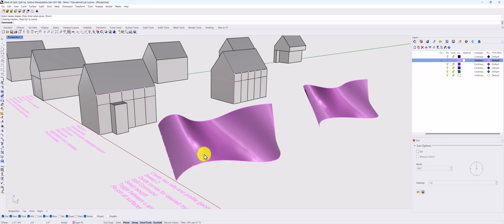And so if I then hit this split command, objects to split, and then I select also the ISO curve here, that's going to give me the ability to split this surface. And because I divided it, that surface is regular. And then I'm going to toggle the direction. So I hit T, and that then switches to my vertical position.